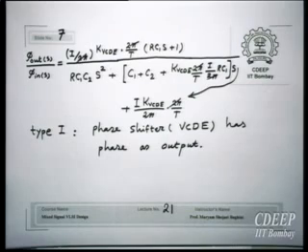It's not like PLL, because in PLL we had different input frequencies, or if we had a divider, we can change the divider ratio to generate different frequencies, and therefore this loop will always go into a transient condition, and then it will come back to the steady state. But in DLL, we usually don't have such conditions. Change at the phase, right?